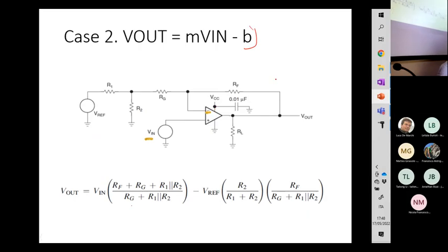In the following case, M is connected to the positive branch, so the input M should be positive, so the input is connected to the positive input of the op-amp, while B is negative, and therefore the reference voltage is somehow connected to the negative input of the op-amp.